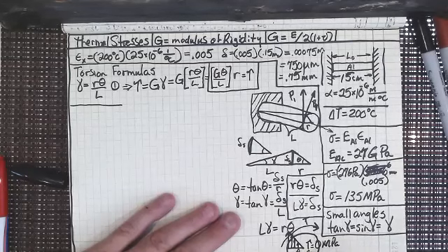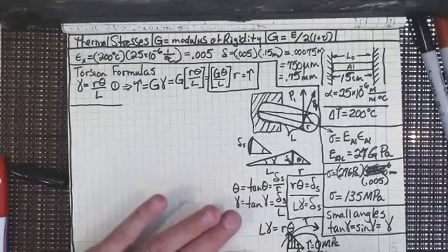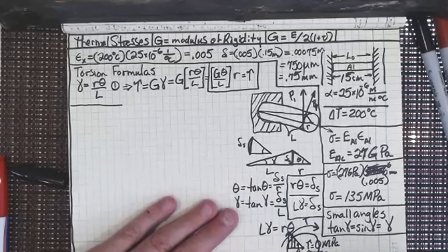So in the center, since R equals 0, the stress is 0. As I go out to the outside, it gets larger and larger. That total resisting force of the steel bar has got to offset the applied force P that we've put on the bar.